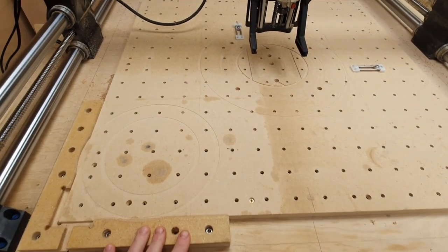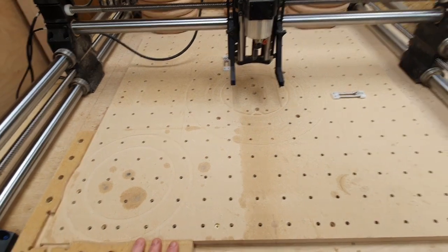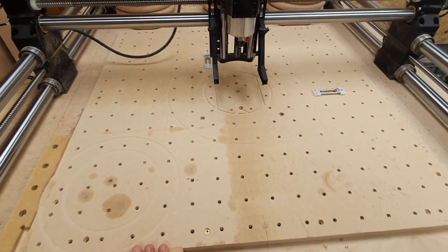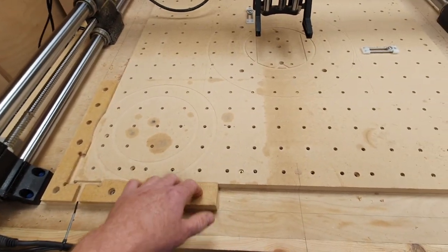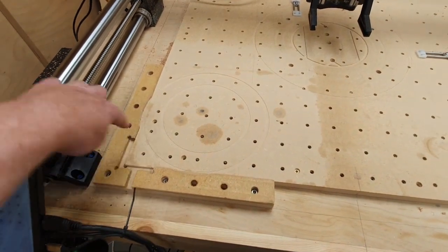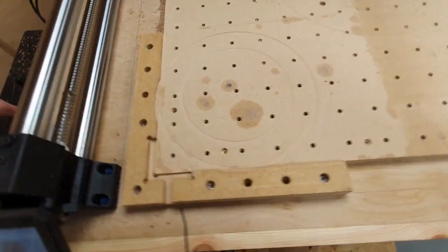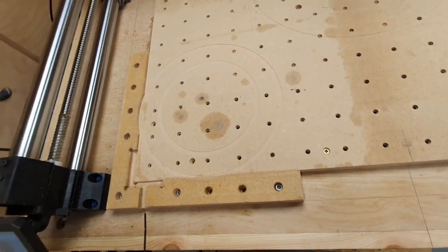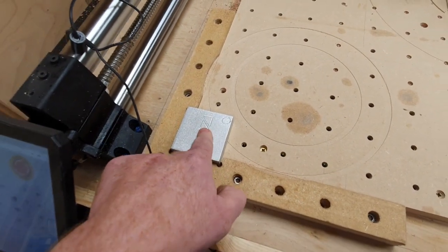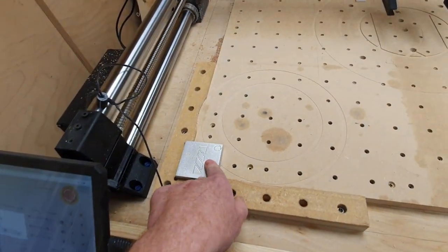Okay, so some of you already know this, some of you might not. If you're waiting for the machine to come and it's your first CNC machine, then you won't know this. But whenever you program the machine to do a job, you're quite often starting from the bottom left corner. That's what this corner bracket's for, and this outlet allows you to put the probe in here, and you probe to this corner, which tells the program where to start the job from.